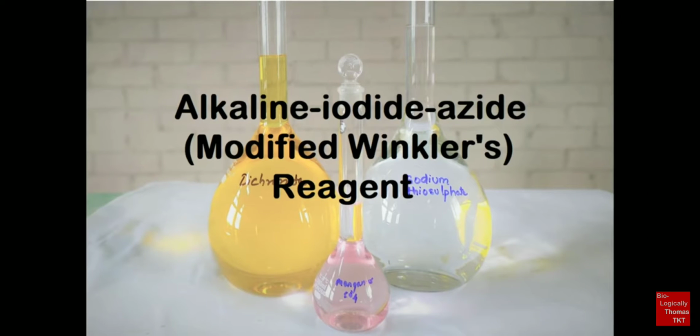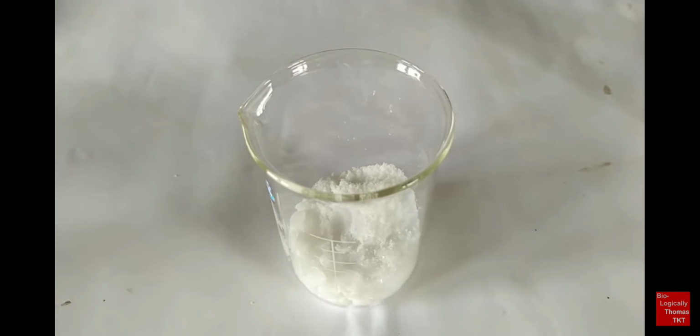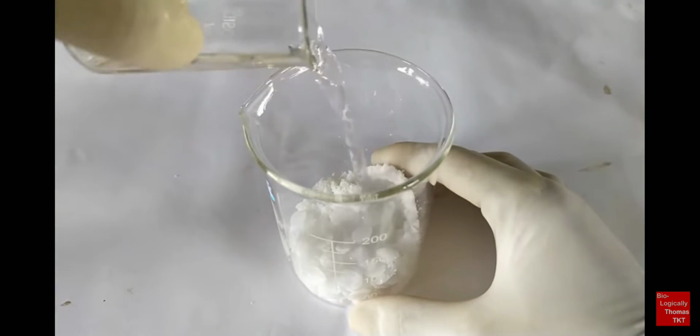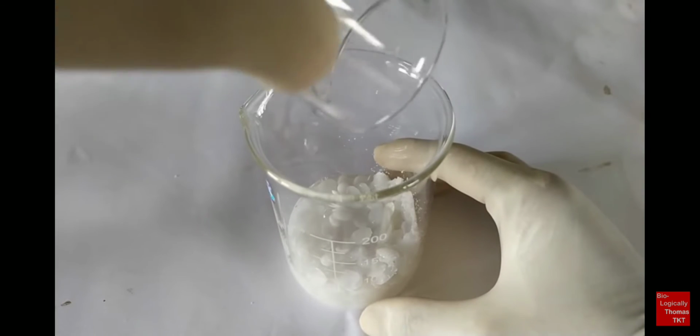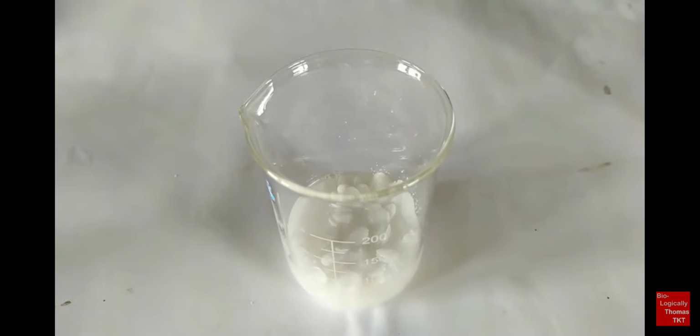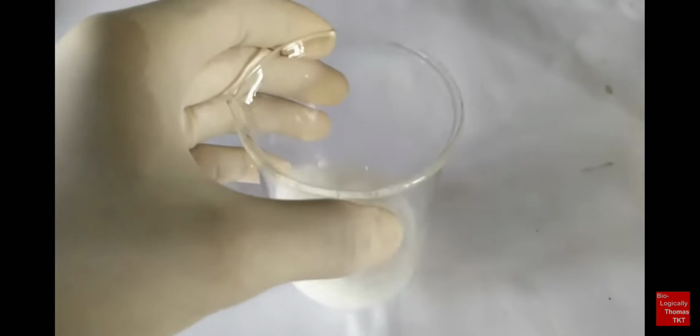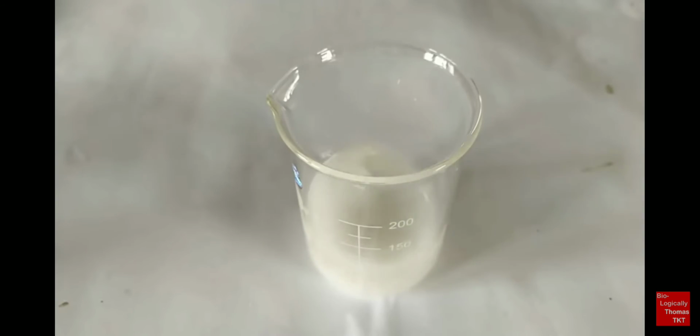The second reagent is alkaline iodide azide reagent. To prepare this reagent, weigh 50 grams of sodium hydroxide or 70 grams of potassium hydroxide, along with 13.5 grams of sodium iodide or 15 grams of potassium iodide in a 250 ml beaker. Add about 30 ml of deionized water. Stir the contents until they dissolve. Allow the solution to cool down and transfer it into a 100 ml volumetric flask using a funnel.